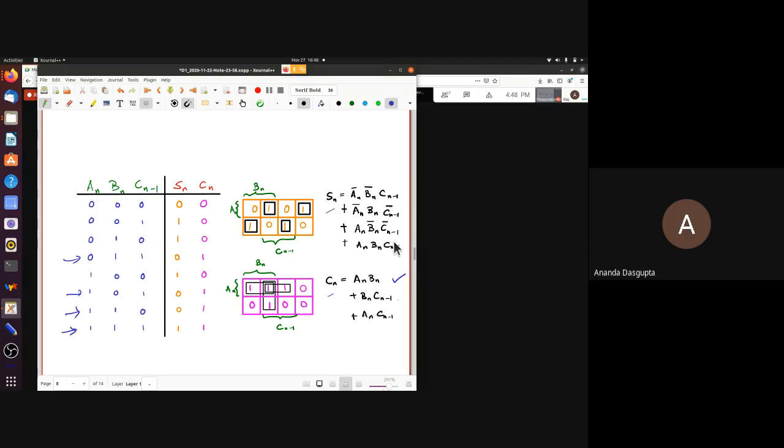Okay. So, because in many situations you would actually want to get multiple outputs, it's very possible that you may have other simplifications beyond what the Karnaugh map tells you. So simplifying such complicated multi-output things is more difficult than just using a Karnaugh map.